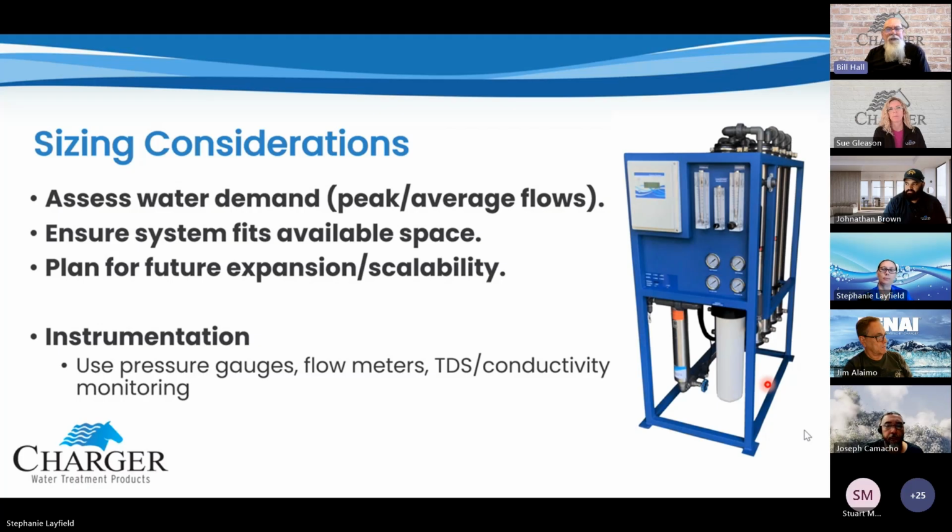Sometimes in the car wash industry, we used to use a tempering valve where we would take hot water and cold water, just like in your bathtub tap at home, and temper it down to get the temperature that you wanted. And we could keep it at 77, and we'd get better quality, better production out of the system. Inversely, every degree you go up from 77, you increase the production of the membrane from 1.5% to 3% or so. So the warmer the water, the more water you're going to produce.